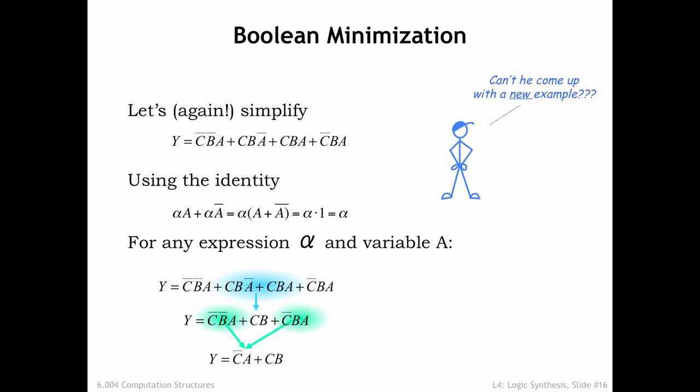Counting inversions and pairwise operations, the original equation has 14 operations, while the simplified equation has 4 operations. The simplified circuit would be much cheaper to build and have a smaller tPD in the bargain. Doing this sort of Boolean simplification by hand is tedious and error-prone. Just the sort of task a computer program could help with.